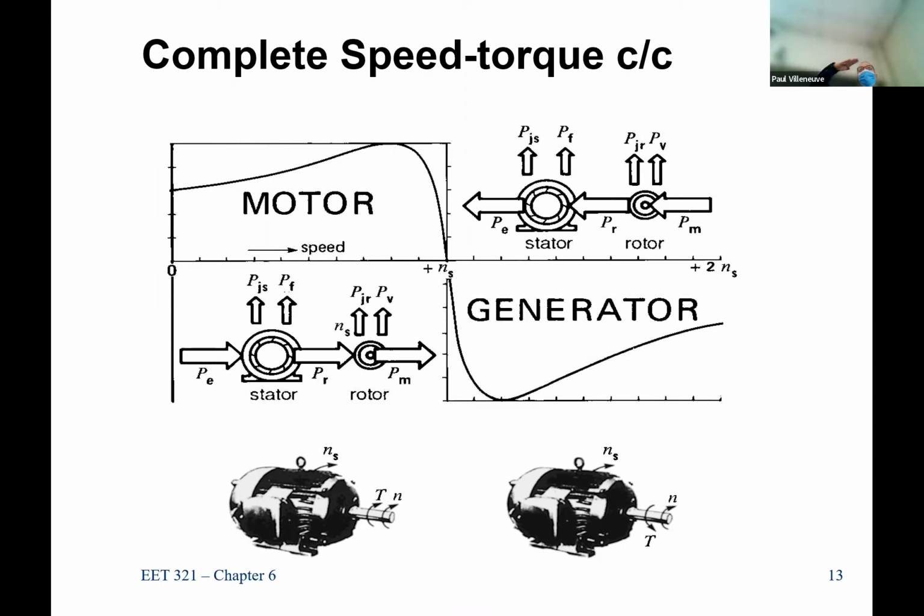So with horizontal axis, the shaft that goes into the generator is horizontal. Vertical axis is this way. So the nice thing is the generator's on the bottom and the blades are up above, so all the weight bearing stuff is really low to the ground. That's a huge advantage. The downside is that those tend to be low to the ground. And where is the wind the best? It ain't close to the ground.